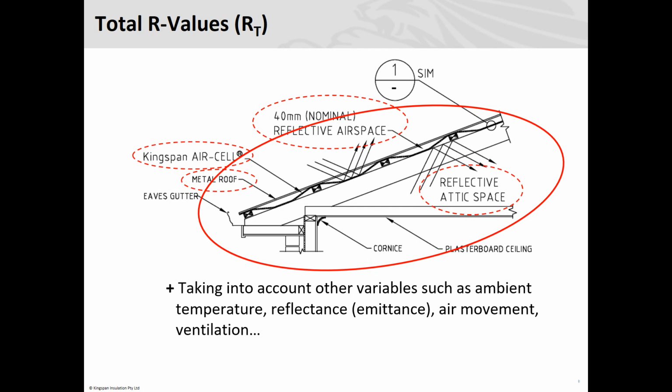So just to touch on this point here though, it's the products that are put into your wall and your roof and your floor systems. It's the insulation values that are put into there, combined with your air cavities and what sort of walling material, whether it be brick, whether it be Hebel, for example, whether it be FC sheeting. So depending on what actual building materials you're using, the whole lot put together is calculated to give you a total R value. But the products on their own have their own R value. That's called material R value. The material R value, that's correct.